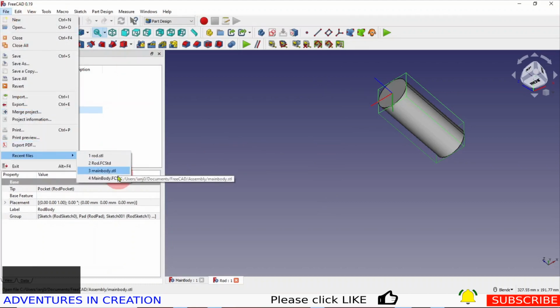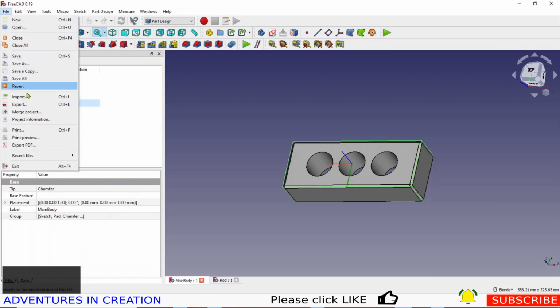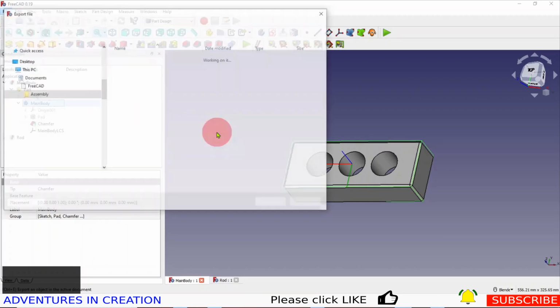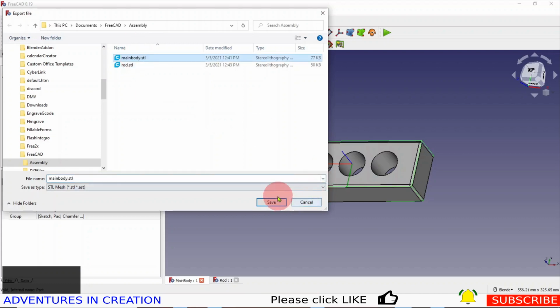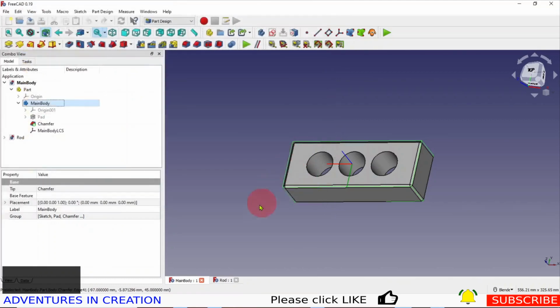You'll remember the main body from the prior one. If you haven't watched that video, go ahead and watch that one, the animation in Assembly 4, and you'll see how we do all this in FreeCAD. I'll put a link to it up top. So I'm going to select this main body, and I'm going to export that, the main body STL, and say yes, I'm going to overwrite that. So that's all I'm going to do in FreeCAD.